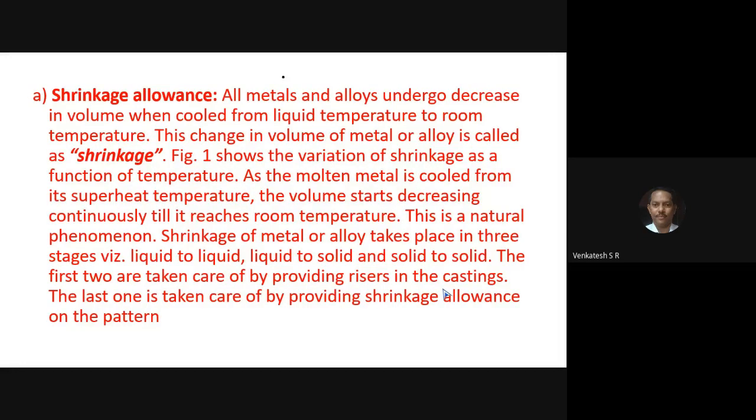Here you have the explanation for shrinkage allowance. Read the explanation twice, thrice, or 4 times or 5 times. Go through the explanation again and again, close the book and write the shrinkage allowance in your own sentence. Shrinkage allowance is nothing but in order to compensate volume contraction. As I told you earlier, the volume of the metal in liquid condition is more when the transformation takes place from liquid phase to solid phase.